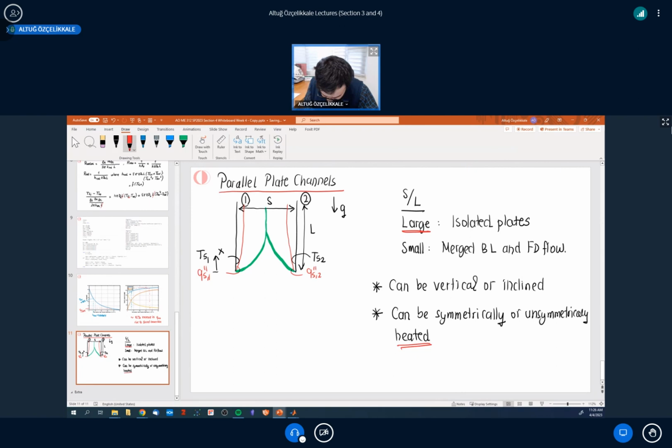Heated means we either have Ts greater than T infinity, so under those conditions that's how there is going to be flow within, or we are simply prescribing some non-zero heat flux. If there is zero heat flux, it doesn't mean there cannot be any surface temperature difference from the ambient, right? So that's kind of a null or trivial condition.